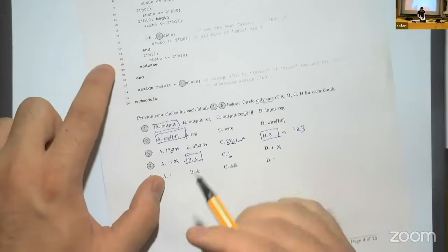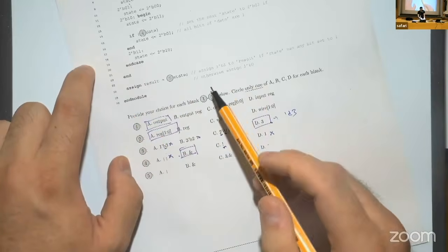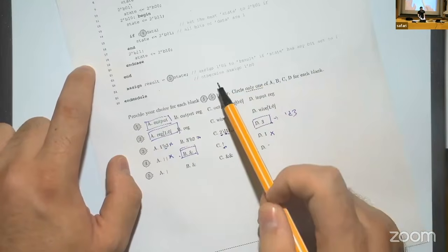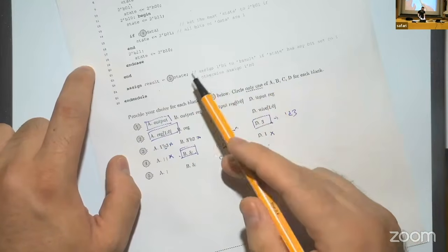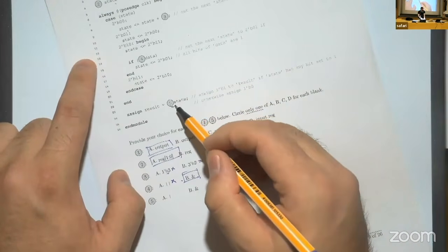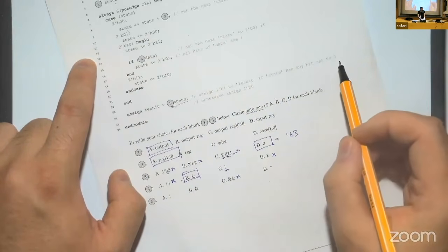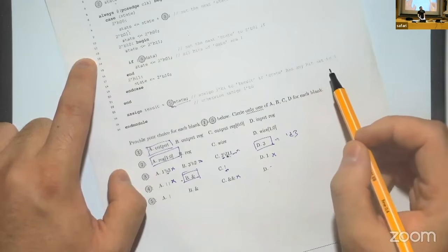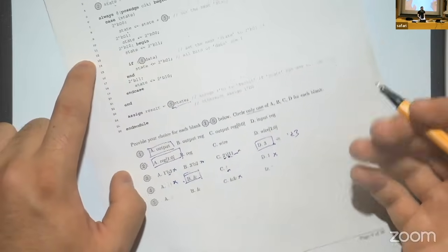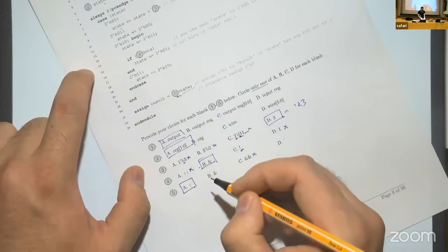The last one is the fifth. It's, again, line 24. It says assign 1 to result if the state has any bit set to 1, otherwise assign 0. We know that it's, again, a similar situation, right? It's at the beginning of the variable, so we cannot use C over there. It also says that it has any bit set to 1. So if any of the inputs is 1, the result is 1. We can easily say that it's OR reduction, which makes it A.